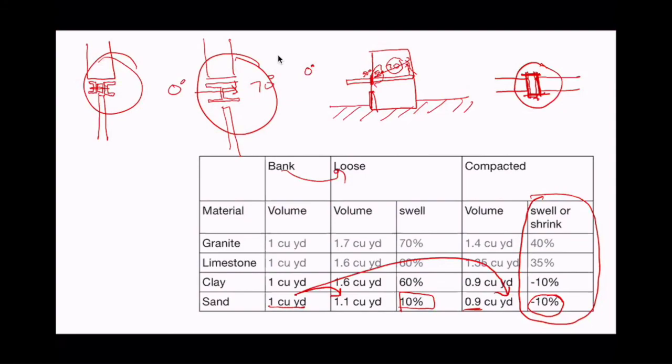Now, in a super high performance building, like a passive house building, where our goal is to use maybe 10% of the energy that a typical building of its kind and its location would use, then we do worry about the bolts going through and things like that. In that case, we probably wouldn't have a balcony. We would just do away with the idea that it has to be exposed on both sides, and we would cover both sides with insulation, or one side with insulation, and then seal it up to the door. Or maybe we'd eliminate the door, because it's hard to make a door insulatively tight.